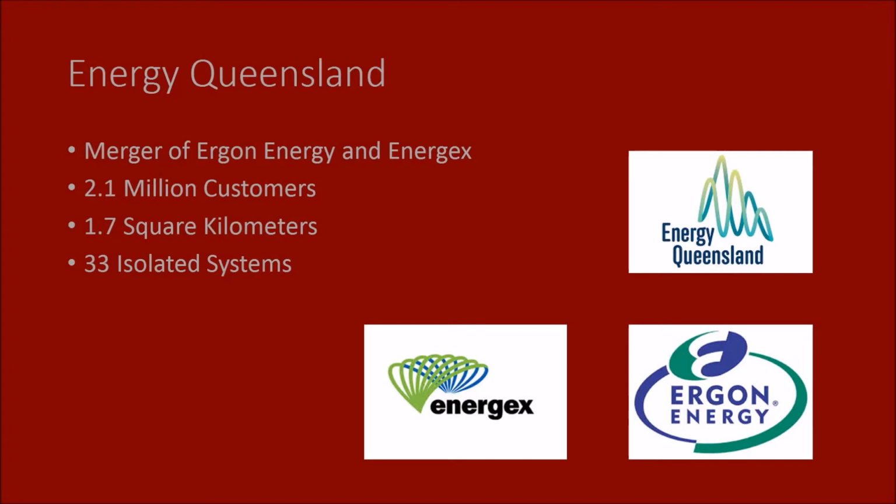Accurate digital models of the physical network are used to simulate augmentations of the network to ensure that asset ratings are not exceeded through new customers, connections, and switching events, calculating harmonic distortion, checking voltage profiles along feeders, and proposing voltage regulators based on findings, amongst others.